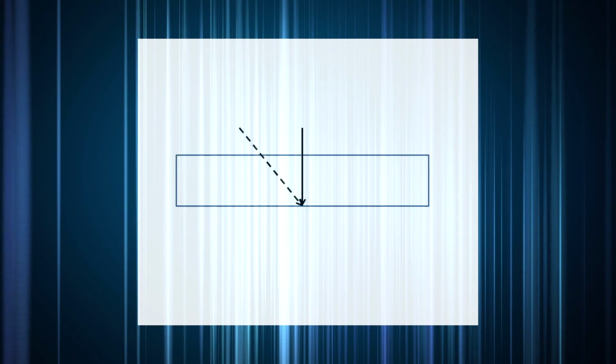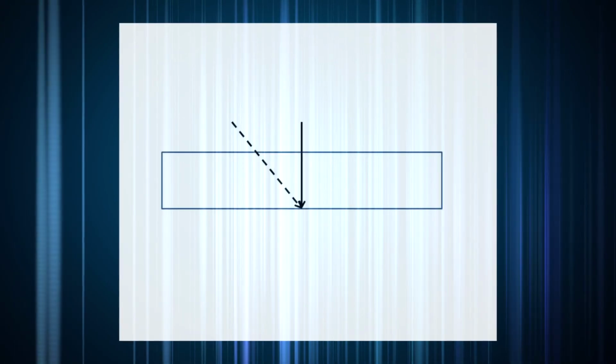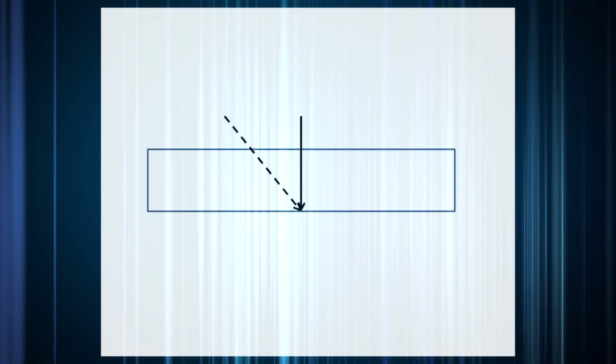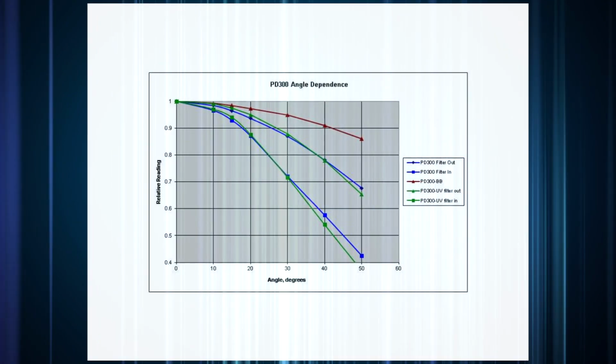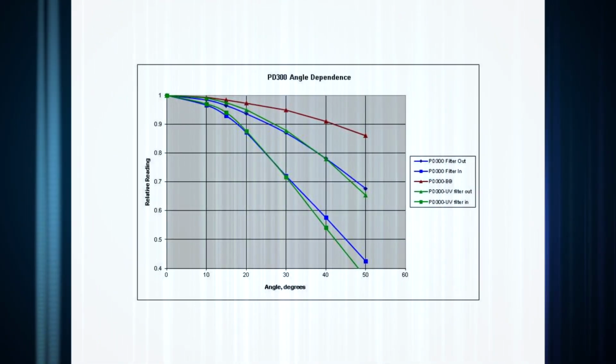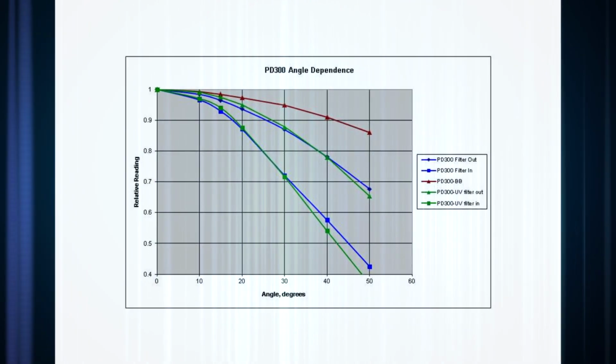Semiconductor response depends on absorption of the beam, which is to a small extent angle dependent. Much more significant though, we have attenuating filters integrated onto our photodiode sensors to enable them to measure higher powers than they otherwise would in order to give a more useful dynamic range. These filters are absorptive, and since optical path through them depends on the angle of incidence, the response will vary with angle of incidence in a more or less cosine relationship.